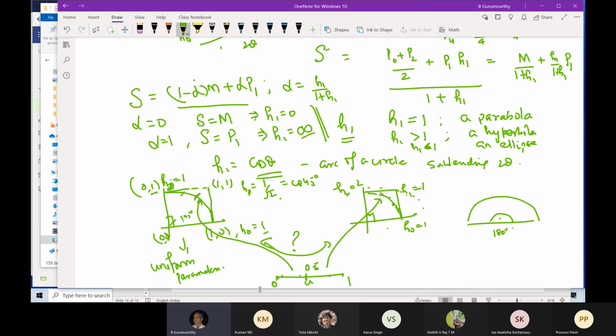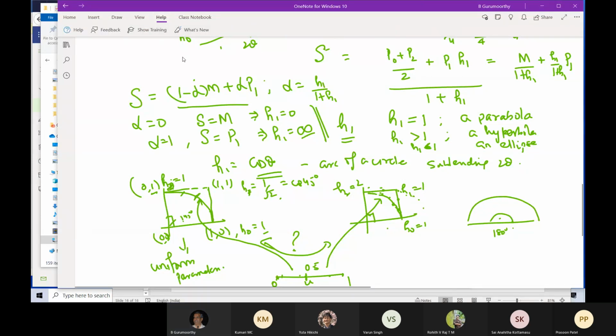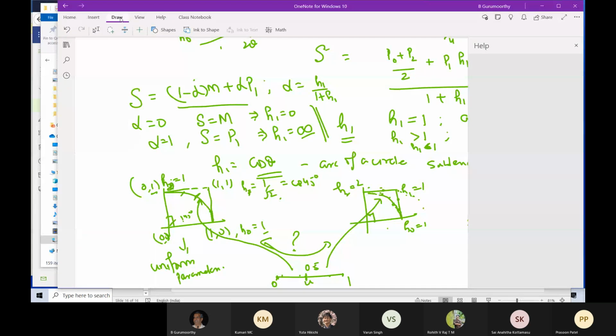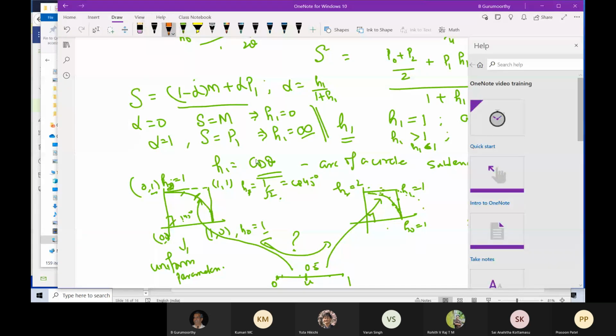I don't know if you remember, when we were talking about the limitations of the Bezier, I had mentioned that you can introduce a new control polygon where one control point is on this leg and another control polygon point is on this leg. And so the new control polygon, let me just take a different color, sorry. So one point is here and the other point is here, so that my new control polygon